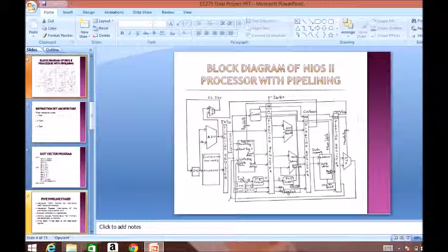Once the program counter value has been fetched and goes to the pipeline register, we go to the decode stage. The decode stage is the main intelligence of the pipeline architecture. We have a register file with read register 1 and read register 2. We select 2 registers, and then check what operation we need to perform, whether it's an I type or an R type.